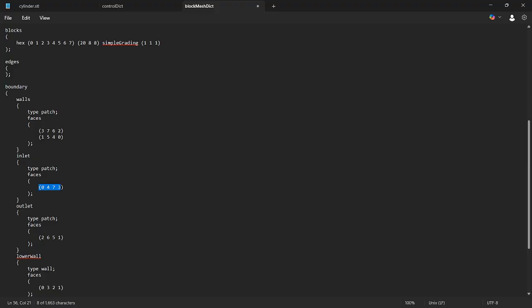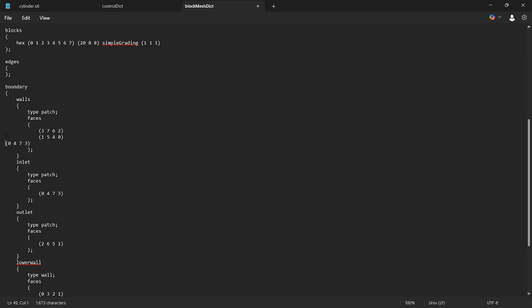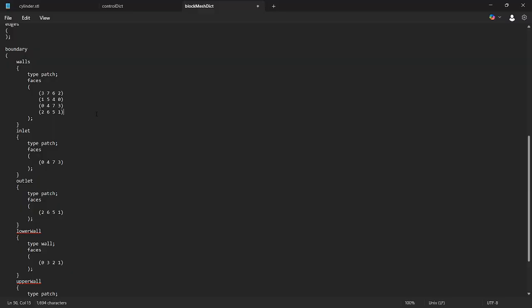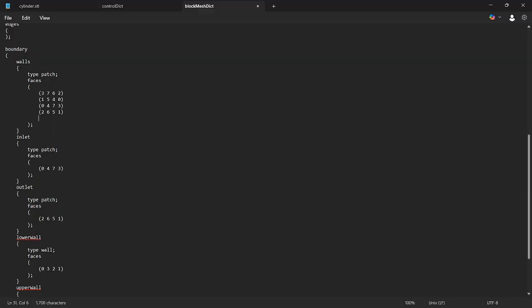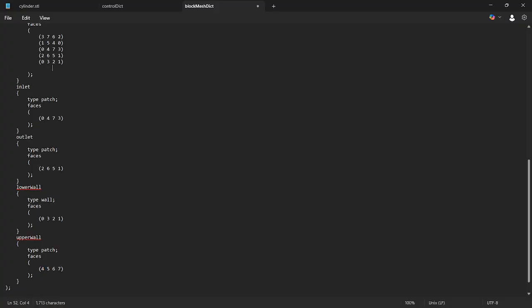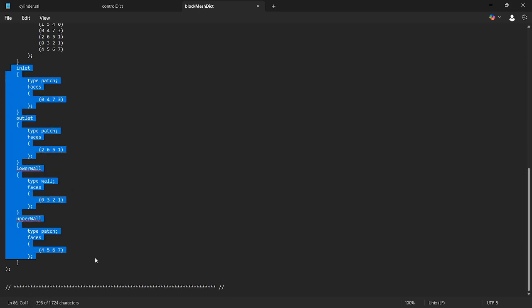Then I'm going to take all the vertices and put them all here, because these coordinates here are describing one side of our block mesh. So take all the sides in the block mesh and put them here, if that makes sense. You should have 6 for 6 sides. Okay, and we can remove all of this. We don't need this anymore.